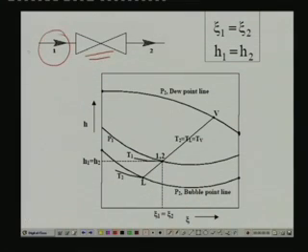A solution at condition 1 passes through the throttle valve and emerges at point 2. If the pressure at condition 1 is P1 and at the exit is P2, you know that P1 is greater than P2. And this is typically an isenthalpic process, so there is neither heat transfer nor work transfer during this process.